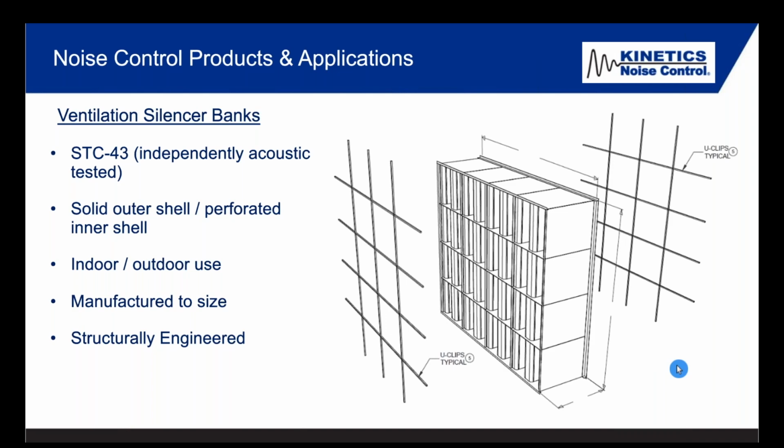And then if it's a large bank of silencers, we can do that as well, but not just sell you a bill of goods that might be small building blocks of silencers, but also help you, depending on the width and height of this, sometimes these can be 20 foot tall and 40 feet wide, determine the added structural steel you may need as backer structural. Even though these have holes in them, what I've always been told by our structural team is you still have to, per IBC, in most parts of the country, you can't give any credit to those holes. You have to treat it like a solid barrier, so it has to have the backing strength.